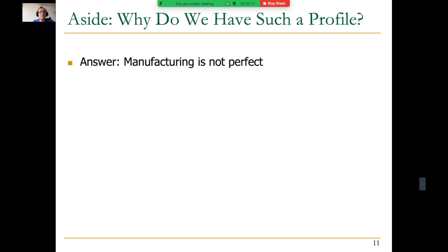And the reason is manufacturing process variation. Basically, manufacturing is not perfect. We do not know how to manufacture every single DRAM cell or every single hardware component to be exactly the same. This is true for actually manufacturing anything, in my opinion. But especially at very small technology generations, this manufacturing process variation becomes much higher, because your control through lithography becomes much smaller. And actually, there's a lot of research that goes into lithography devices so they can cut things in much better ways, but it's not a perfect thing. So your control is much lower at very small dimensions.